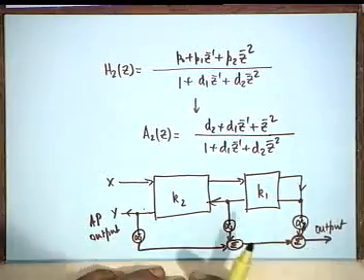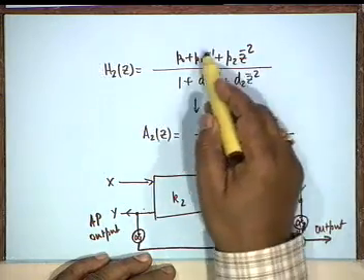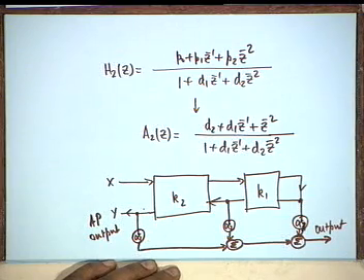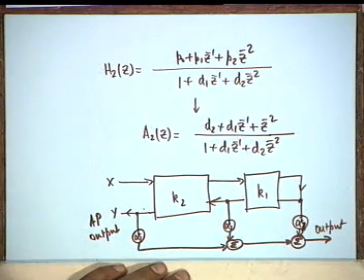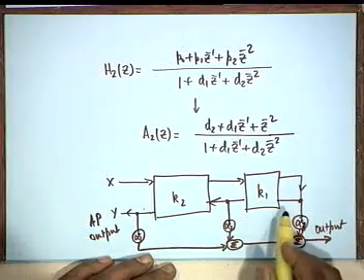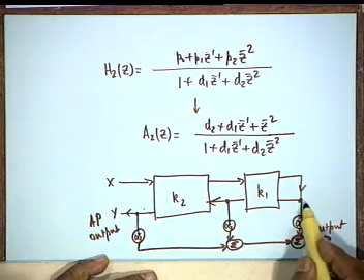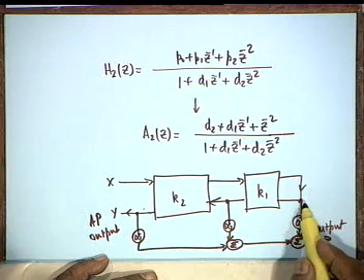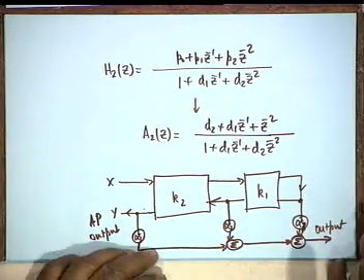Is it logical that they would match? That is, is it guaranteed that we shall be able to get a numerator like this? I have three given parameters and I have to choose 3 unknown parameters. So, it should be possible. Degree, is the degree all right? I use 2 delays here and therefore, this is after 2 delays, this is after 1 delay and this is without delay. So, it should be possible. Second order, any numerator can be realized by using taps. Okay? Once we are sure it can be done, then we proceed.